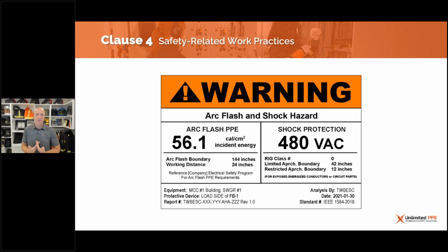I have yet to hear of any workers dying from an arc blast. If you're wearing arc flash PPE, you're gonna survive the incident. If it's adequately rated and it's worn properly and it's suitable for use, meaning it's not covered in some hydrocarbons like oil or grease, you're gonna be okay for the most part. I know we mentioned in the standard that there could be minor injuries, that we can't cover everything with arc flash PPE, but there's certainly no limit at 40 calories.